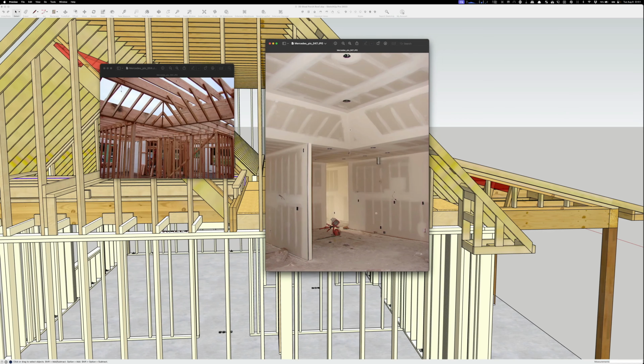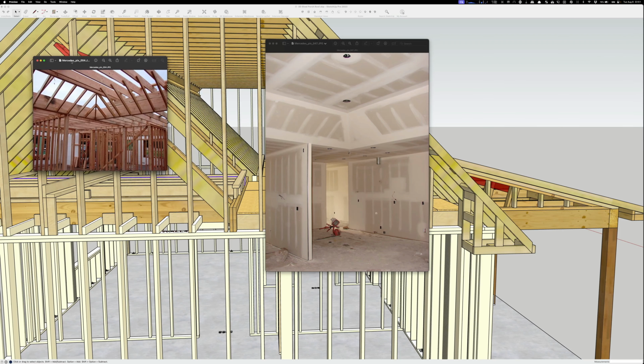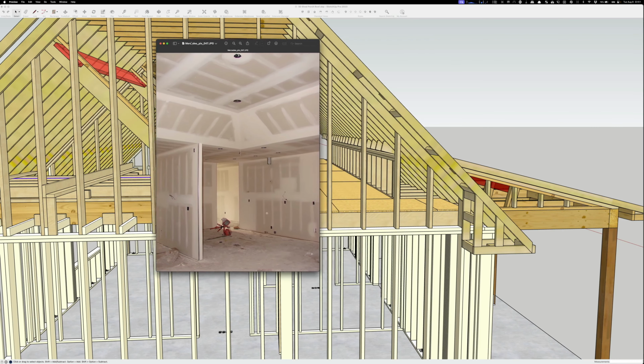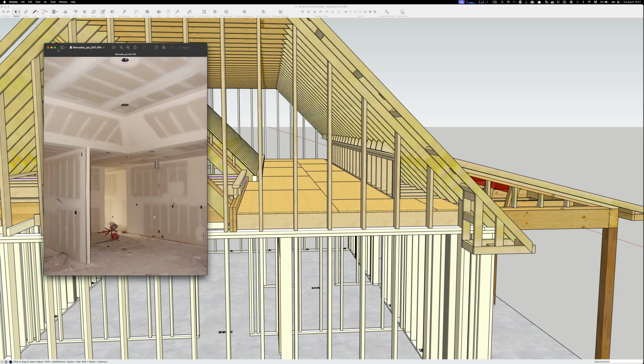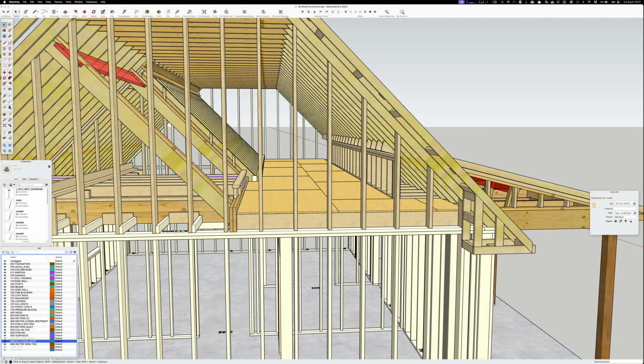So you get that sloped sheetrock look, and it's just custom. You can do this with trusses, but as soon as you start making custom trusses, they get expensive because they can't reuse the same jig often. They have to reset for each truss, so you're going to pay for that.